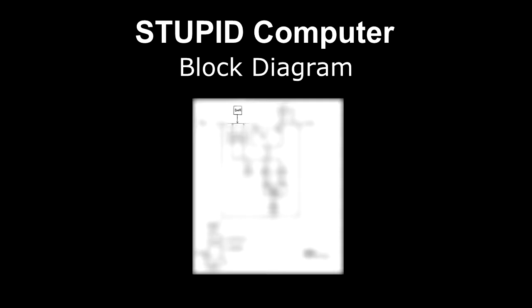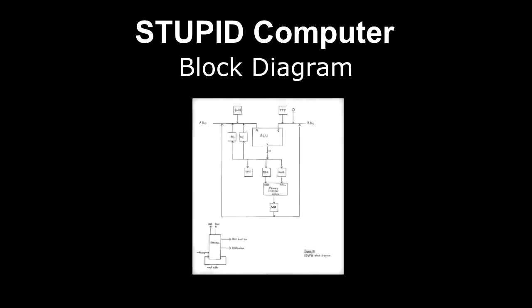Other registers, there's MAR and MWR, memory address register and memory write register, and then a memory buffer register, which wraps back around to the buses there, the A and the B bus, which then feed the inputs to the ALU. So every instruction that involves data, and that would include a jump where you're modifying the program counter, passes through the ALU.